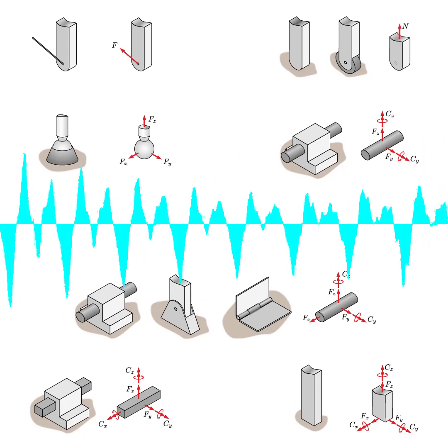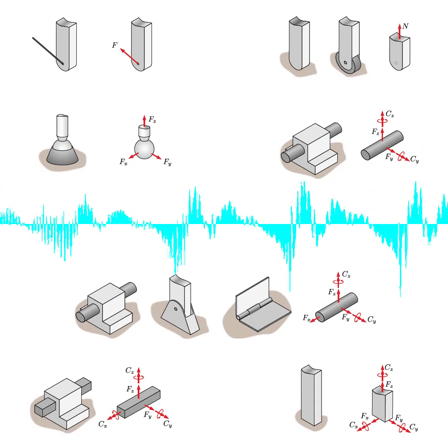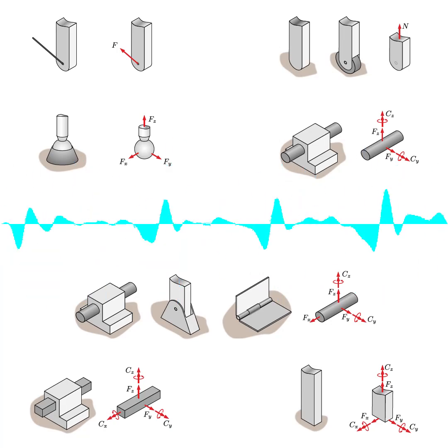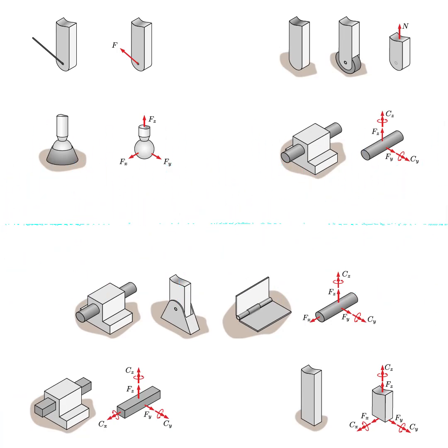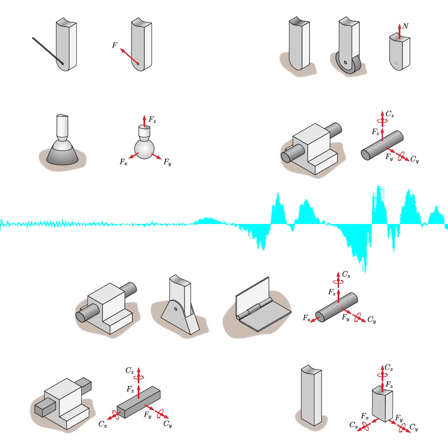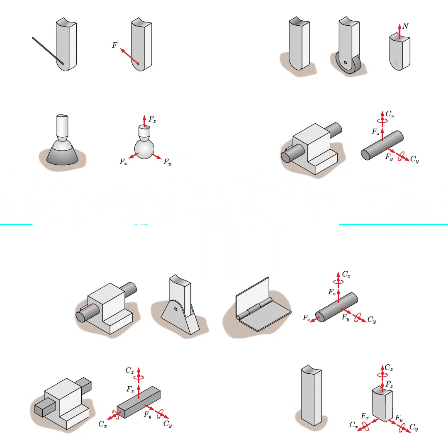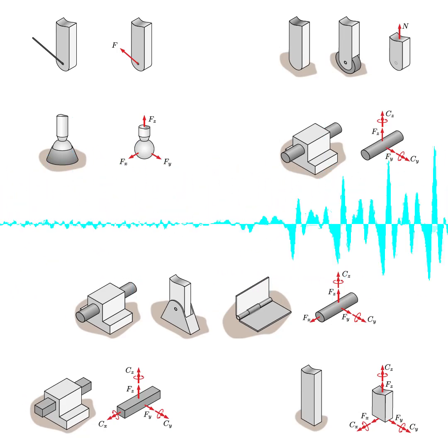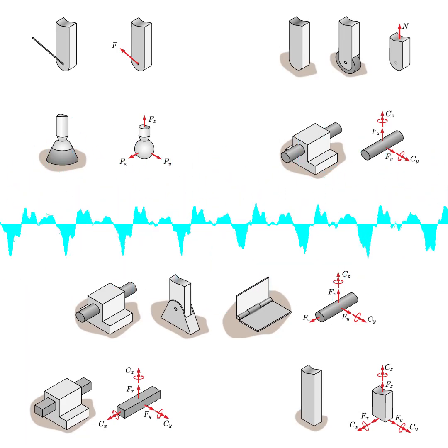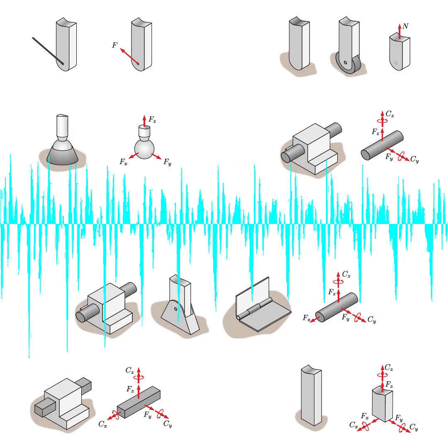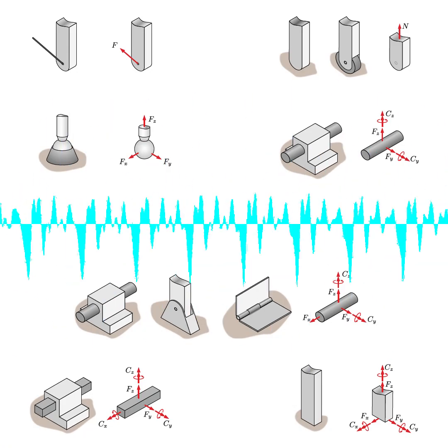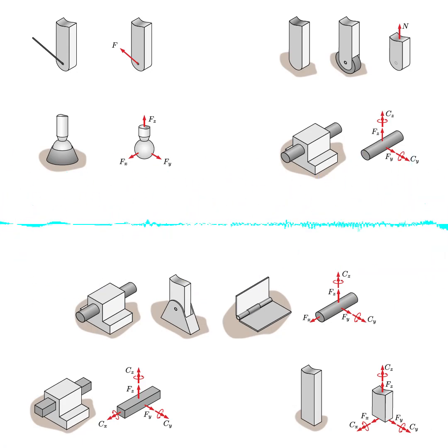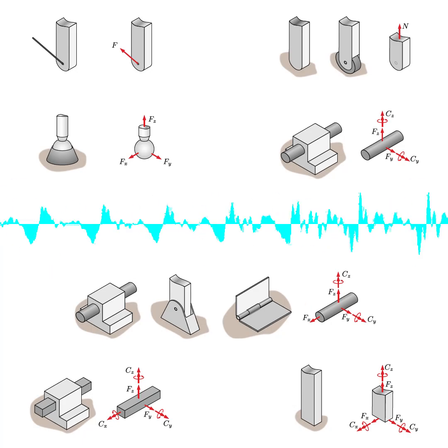Nice. Okay, so moving on now to section 5.5 and 3D rigid body equilibrium. The source points out that while all the basic principles are the same, things do definitely get more complicated. What are the main challenges we run into when we're dealing with equilibrium in 3 dimensions? Well, the biggest challenge is that you have more degrees of freedom to account for, and it's also just harder to visualize the forces and moments when you're working in 3D space. Now you can have up to 6 unknown reactions, and the moments are no longer just about clockwise or counterclockwise rotation. Right. You have moments that can cause rotation around all 3 axes.